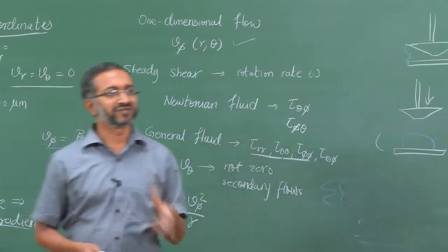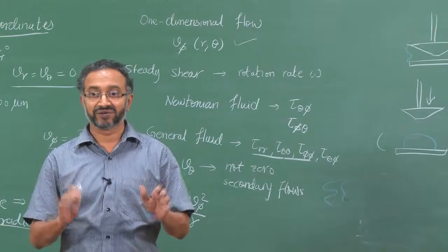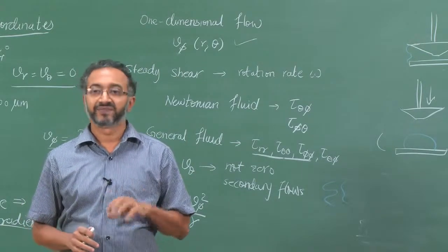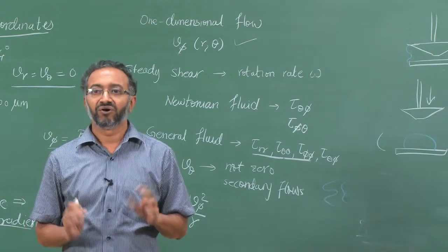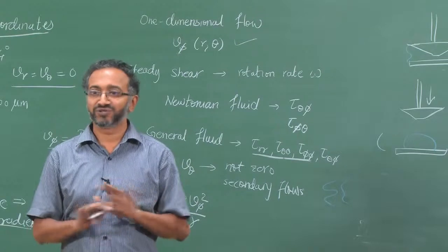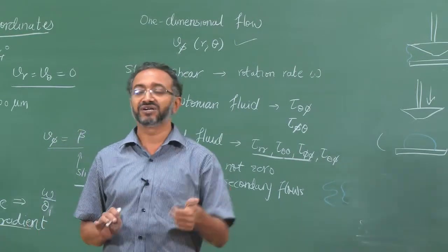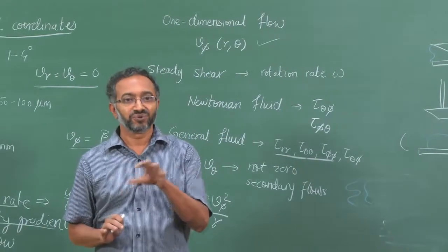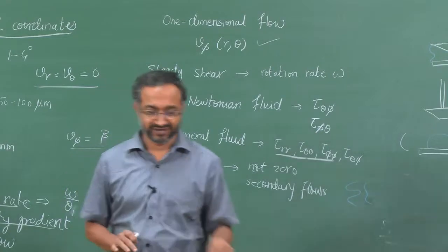So when you are working with a new material, it is always better to first load the appropriate amount and do some tests, then just for trial load a little bit extra and see what happens to the results, or load a little bit less and see, and qualitatively the differences should not be there. Quantitatively the results will be different, but if suddenly you see a qualitative difference, then you know that under some conditions there are some artifacts in the material.